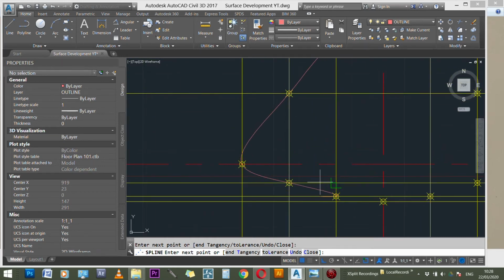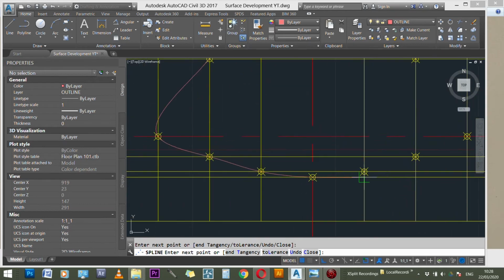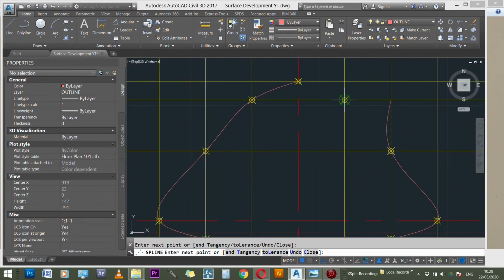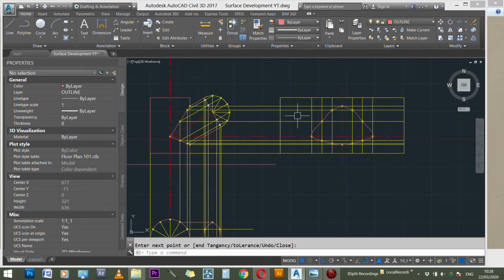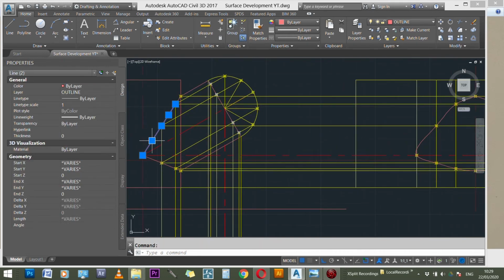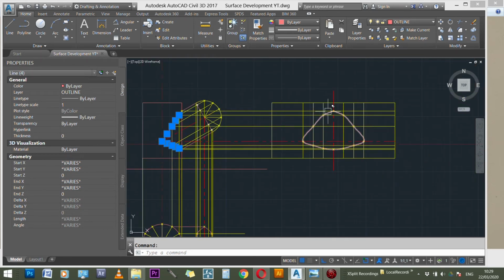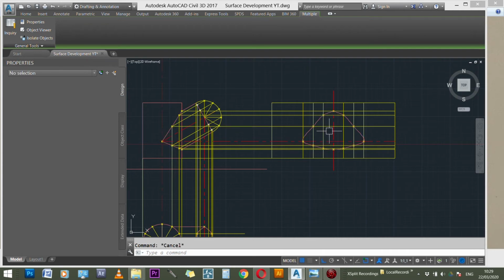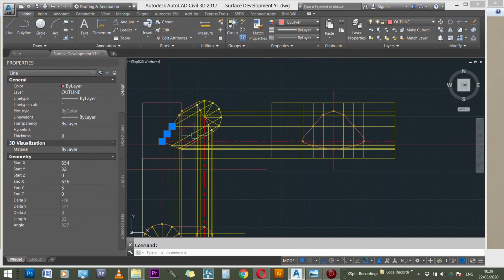Now all of this will be rolled all the way to form the cylinder of diameter 60 millimeters, and once it is rolled, then this hole here will turn. You won't see this hole like this shape. When it is folded, the shape will look like this line here once it's rolled and turned into its elevation. But once we unfold it, this is what the shape will look like. So these two are extremely similar. So this drawing, which is our front elevation, influences the development.